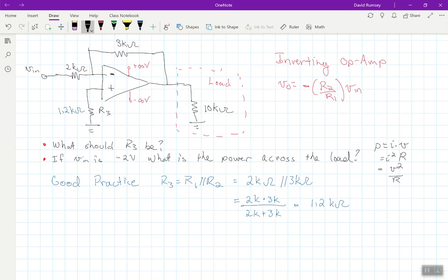Now, one thing I want to emphasize is if you're talking about an output here, you never can determine what the output current of this op-amp is directly. And what I mean by directly here is we can't just assume that, oh, it's 1 milliamp coming out, or do a simple computation. We could eventually figure it out, but what we want instead here is to know what the voltages are. Now, I didn't label anything here, and I did that on purpose, because we should be able to recognize that right here, if I put a little terminal here, this voltage that I'd measure would be the output voltage. That's clearly the output of the op-amp.